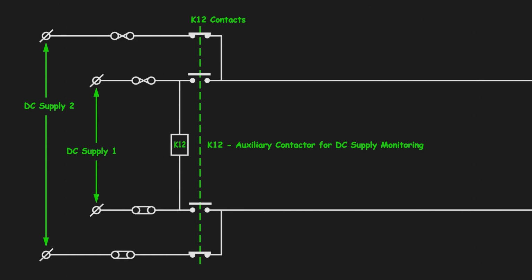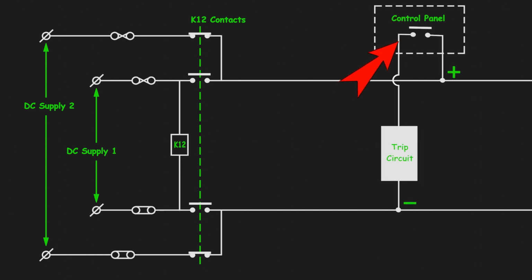There are generally 2 schemes. Some manufacturers and utilities prefer that the DC signal of the circuit breaker be sent to the control panel, and from that control panel, the normally open NO contact of a relay or switch comes back to the tripping circuit of the circuit breaker, so that whenever the relay contact or control switch contact closes, DC will go to the control panel and return to trip the circuit breaker.